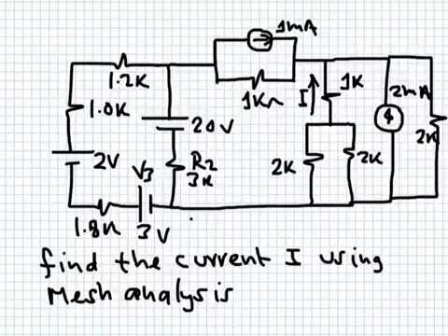Of course, in mesh analysis, and as we explained in classes, it's better to get rid of all the current sources that you have. Mesh analysis is done in an easier way if you have only voltage sources. This does not mean that it's mandatory to remove some of these sources. Some of them will not cause any problem, but let's make it a standard procedure. If you have a current source like this one in parallel with the resistance, it's better to replace them by one voltage source in series with the resistance. This, as you see, will simplify things a lot.